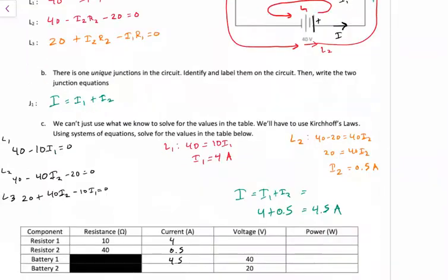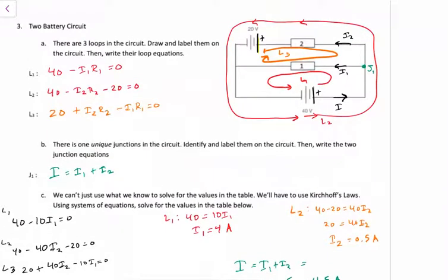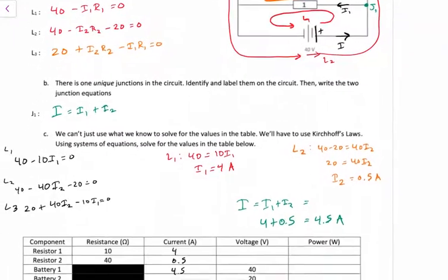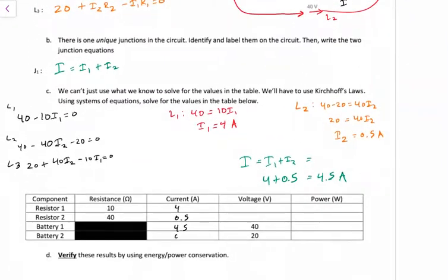They are technically in series with each other. So the current passing through my second resistor is equal to the current passing through this battery, just going against the battery's push, but that's because the 40 volts is greater than the 20 volts. So this must be 0.5 amps, which makes sense that it's so much smaller because this battery is pushing against it.